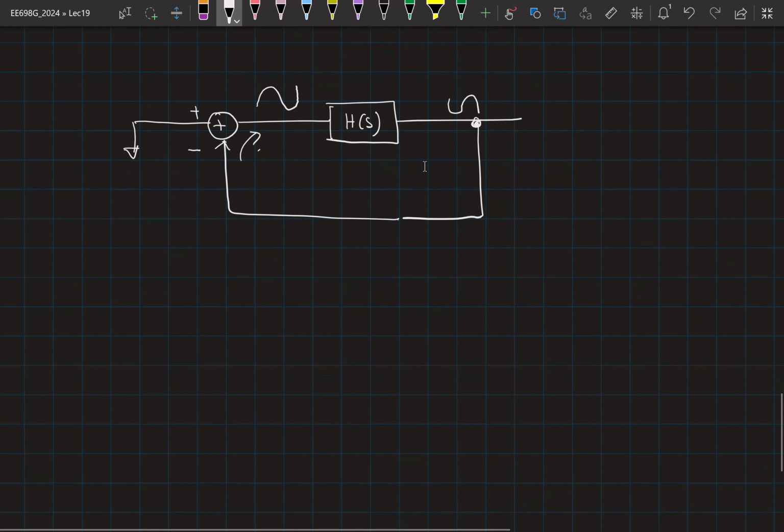At the start, we give one sine wave and take out the input. So you are initializing the circuit, right? Do you have to give a sine wave in particular, or can you give small noise? If you want small noise, at the end of the day it is positive feedback, right? It will keep building up till it reaches the supply. Correct. So any small noise should technically do the job. But that will not end up as a sine wave, right?